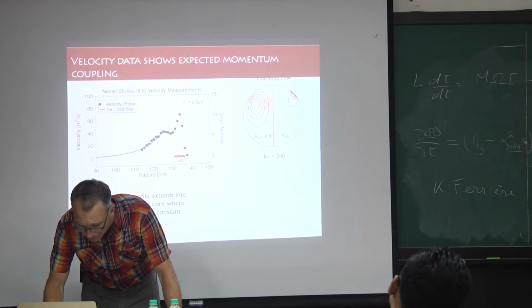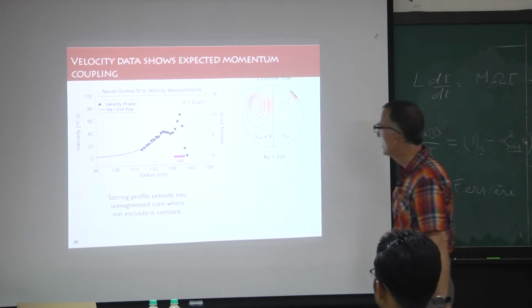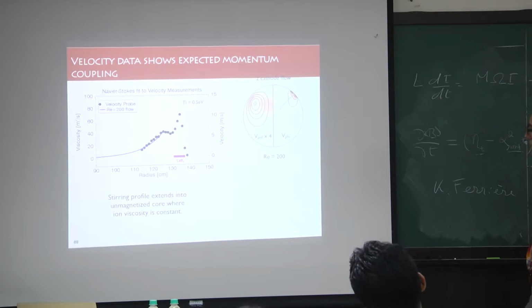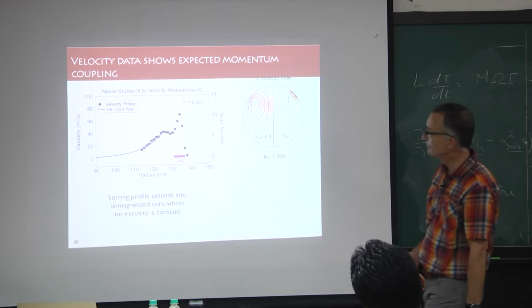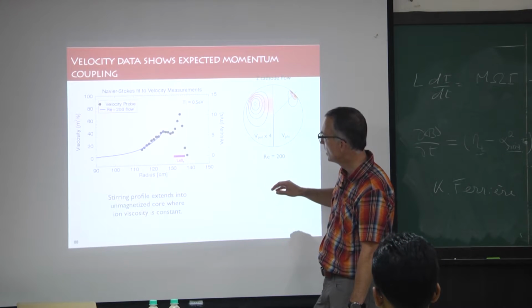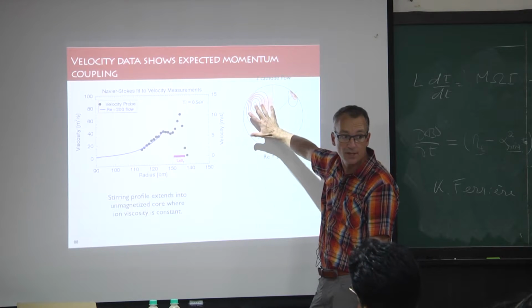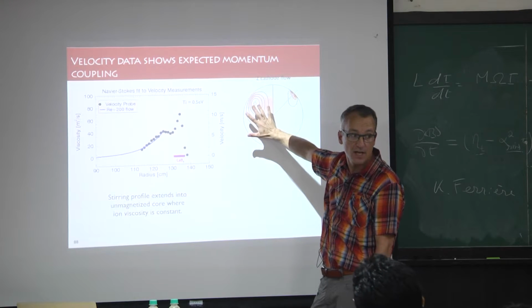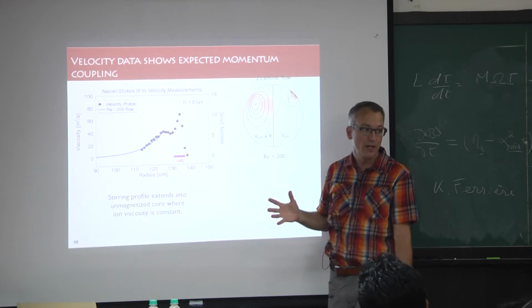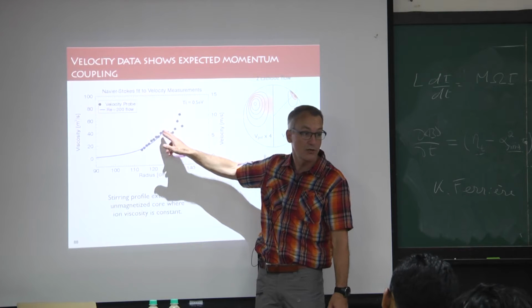Now, you can actually use this as a viscometer. We can solve the Navier-Stokes equation given what the fluid Reynolds number is. That's essentially a measurement of the viscosity. If we knew what the fluid Reynolds number is, we would know what the viscosity is because I know what the peak velocity is. That's what I'm measuring.